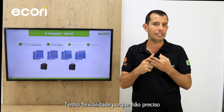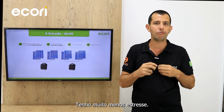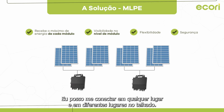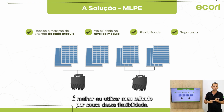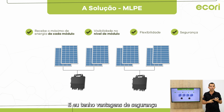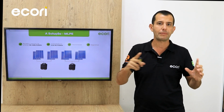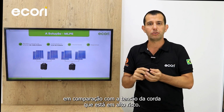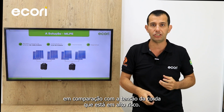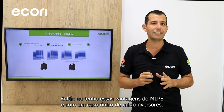I have flexibility because I don't need to have a certain amount of panels in a string. I have much less restraints. I can connect everywhere, different places on the roof. I better utilize my roof because of this flexibility, and I have safety advantages because I don't have now a string of very high DC voltage. I have only one or two panels' DC voltage, which is safe compared to the string voltage, which is high and dangerous.